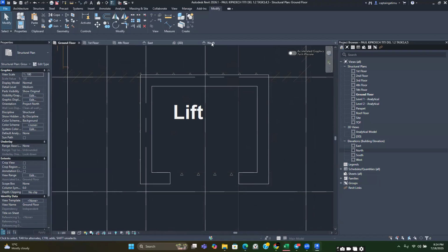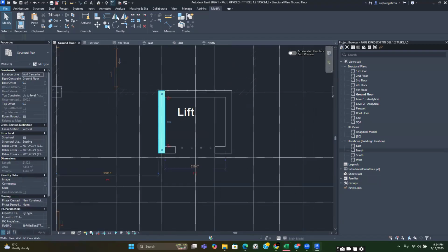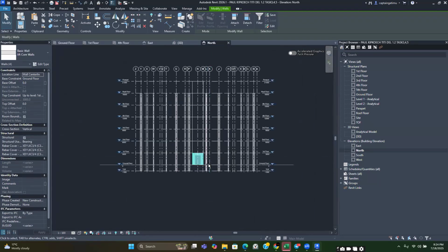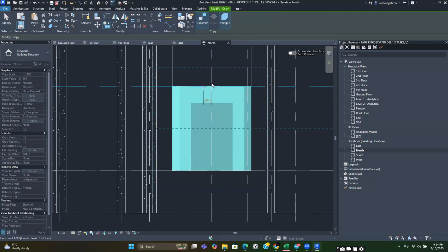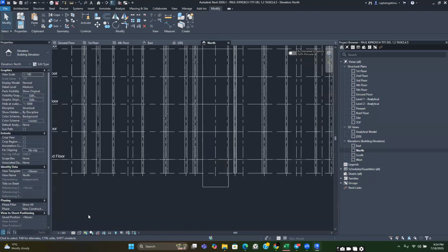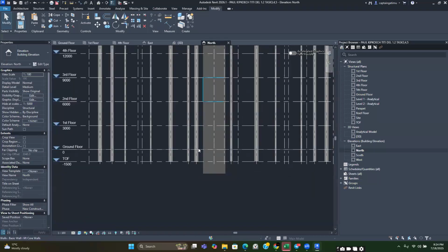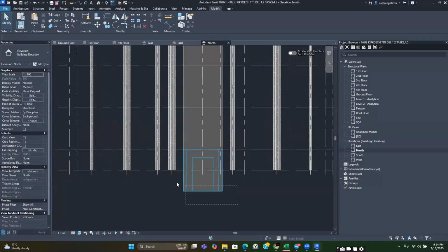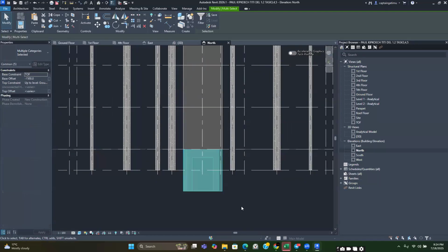Walls and then go to your elevation view and just copy them from the top parts to uncheck constraint. Copy them from the top parts to this bottom part, and you're good to go. So let me turn on shaded, and you can see our wall there. So after you have this, you can just highlight this section over here, select all those walls.